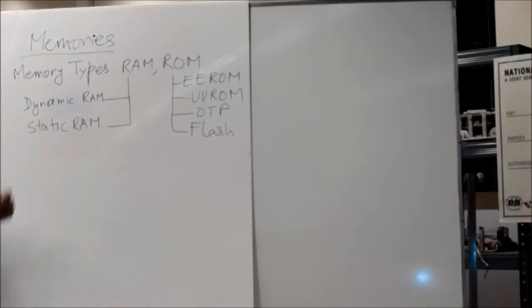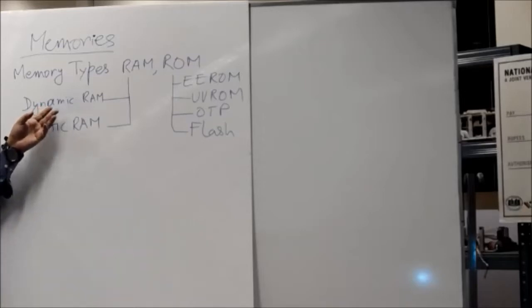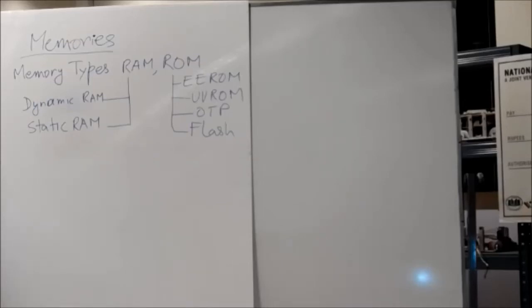A dynamic RAM, on the other hand, requires a capacitor to store a charge. A capacitor that is charged is said to have a stored value 1, and one that is not charged is thought to have stored value 0. And since capacitors lose charge over time, they need to be refilled, updated, what in the world of DRAM we call that you need to refresh data.